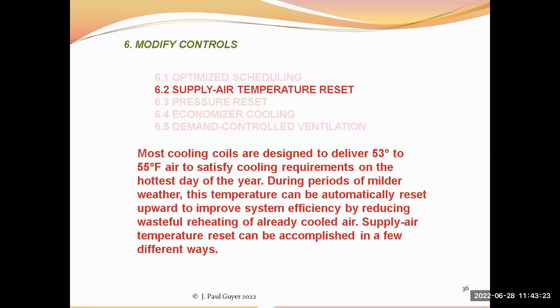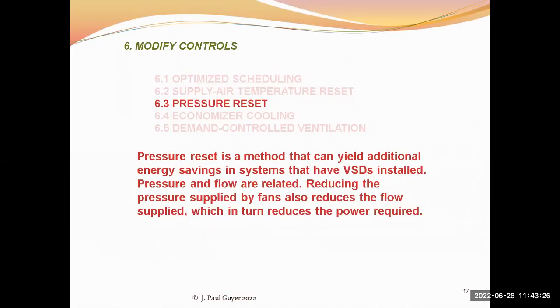Pressure reset is a method that can yield additional energy savings in systems that have variable speed drives installed. And pressure and flow are related. And so reducing the pressure supplied by fans also reduces the flow supplied, which in turn reduces the power requirement. So pressure reset is an opportunity that may exist with the control system for the HVAC.